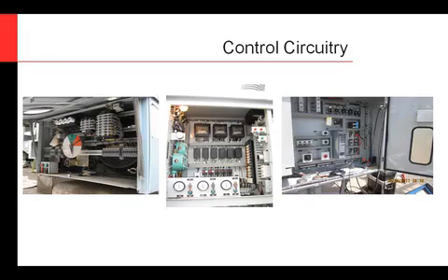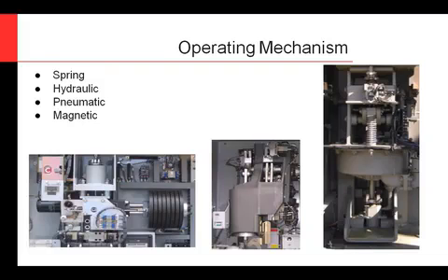So the operating mechanism, as I said, drives the interrupter. This opens and closes the breakers. And you'll have many different designs. You have spring, hydraulic, pneumatic, magnetic. One of the most common designs is a spring-spring design. The reason we use a spring is because it's really the simplest mechanical device that we can think of. All you do is you charge this spring, and it's sitting there ready to go.